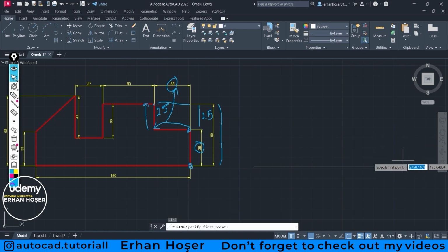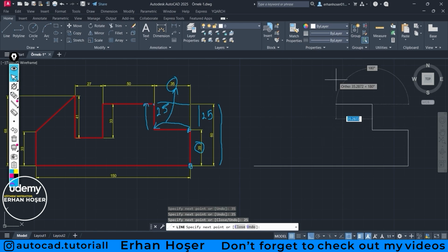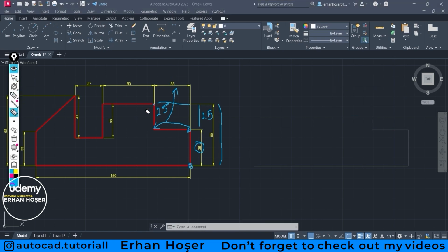I pressed L, I pressed space. I clicked the last point once and pulled my mouse up. I did 35, enter. We will go to the left side, 35, enter. We found the upper part 25 units, 25, enter. I pressed escape, exited the command. We are at this point right now.